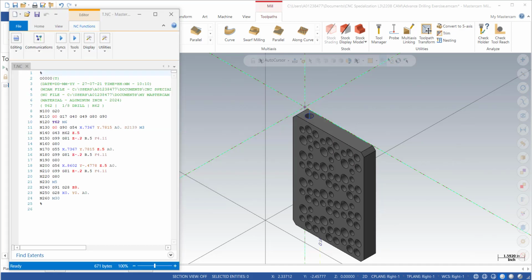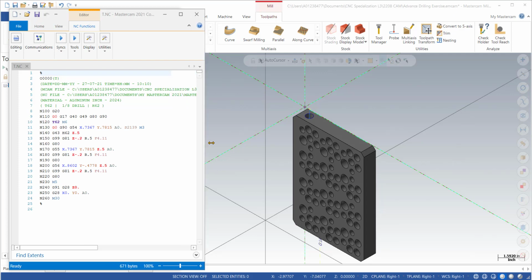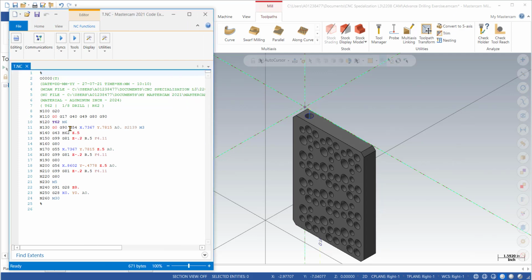Okay. So now if we look at the codes, you can see there is G54 coordinate right here, and then G55. They are exactly the same as G54 because we picked up that corner. G55, sorry, and then G56. That's the coordinates for the side hole. So as per our view on the screen, from that corner, that's the distance of that hole.